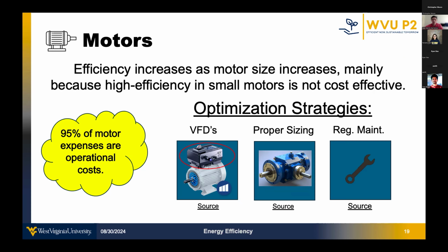This includes lubrication of the motors, using the specific amount and type of lubricant, checking for alignment issues, and replacing worn parts. Proper maintenance can prevent energy loss and extend the life of the motors.